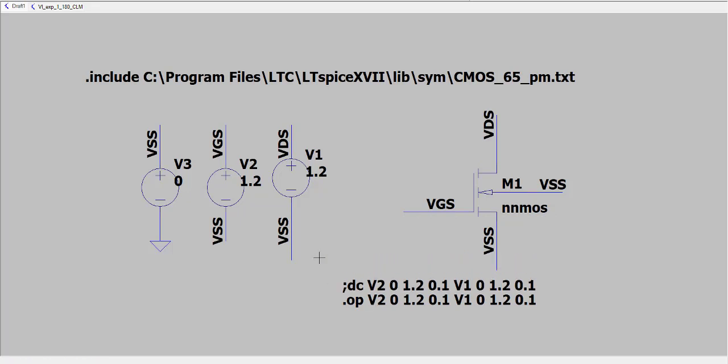Okay. So you see, this is a basic MOSFET. This is an NMOS, and I have applied these voltage sources. Using these voltage sources, I am applying a gate to source voltage so that I am biasing the MOSFET, right? So we have the VGS, we have the VDS. I have kept the names just like we write in the formula. So you all know the formula, so keep that formula in front of you. We will see how we get the DC characteristics.